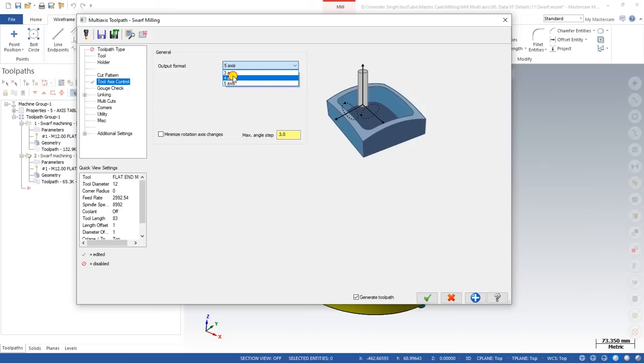If you are using a 4-axis tool, or if you are using a 5-axis tool path, make sure your A, B, and C go from 3+2 code to NC output, and two things will become A or C, A or B, or A, B or C. But if you want my tool to become 4-axis only, you have to define the 4-axis and on which axis my rotary has to rotate. So you have to define X, Y, or Z. According to that definition, my next axis will be added on.